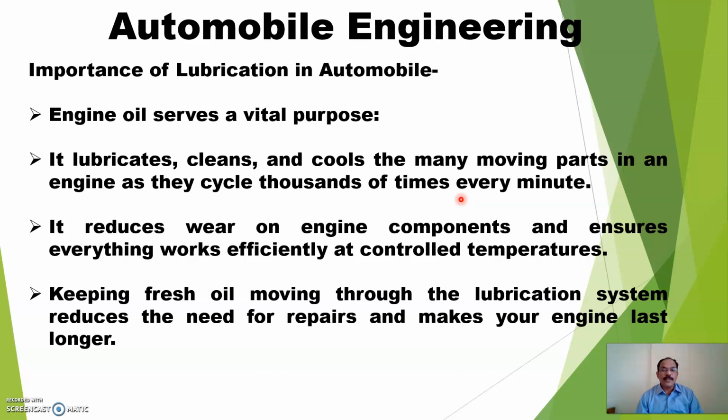So we need to lubricate these parts, otherwise the life of the part will be reduced. They will not be able to work for a longer period. So lubrication is very essential as far as the IC engine is concerned. Also, it reduces the wear on engine components and ensures everything works efficiently at controlled temperature, because the main purpose of lubrication is to lubricate, but at the same time it also carries away the heat generated during the combustion from the component, so it cools.